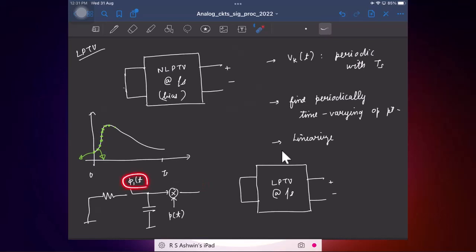I also have these clock blocks. I have written it as a block diagram, but finally this will be going into some node. So basically in this circuit, these clock signals are the voltages that vary periodically with time. And of course because of these clock signals, the circuit is also periodically time varying, right?